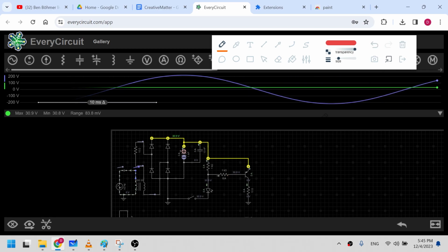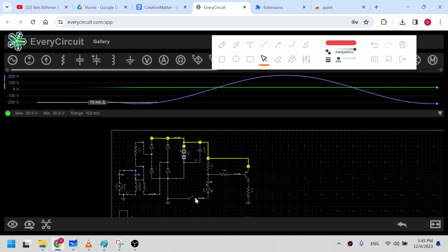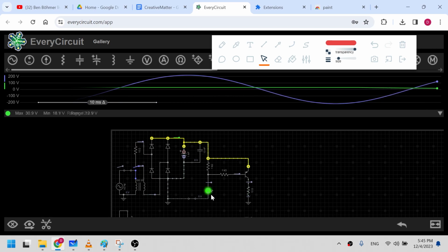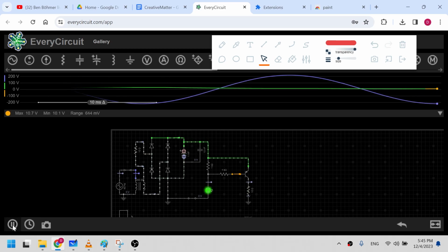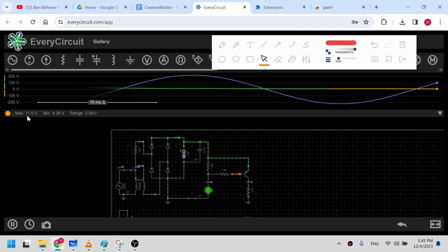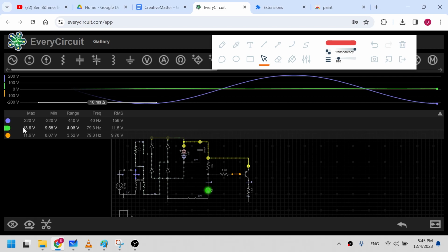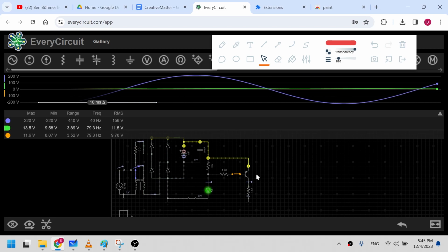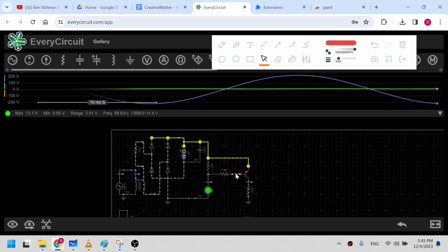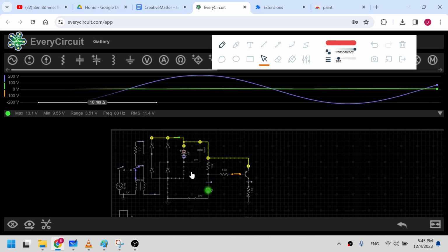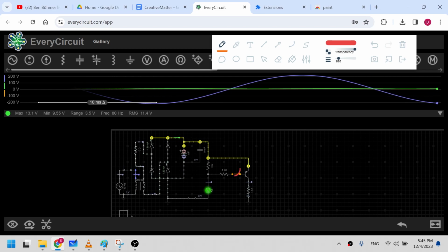Now if you connect this switch, let's see what happens. See what the voltage is here. You can see orange is 11.6 and green is 14.13, so there is a delta V voltage gap between this emitter and base. So a net current flow is there in this direction.